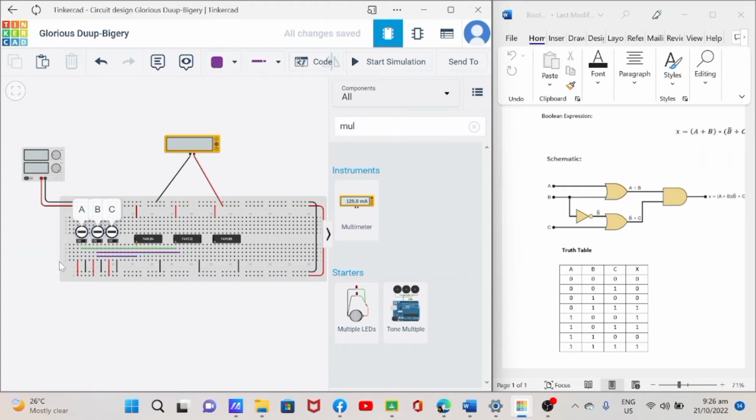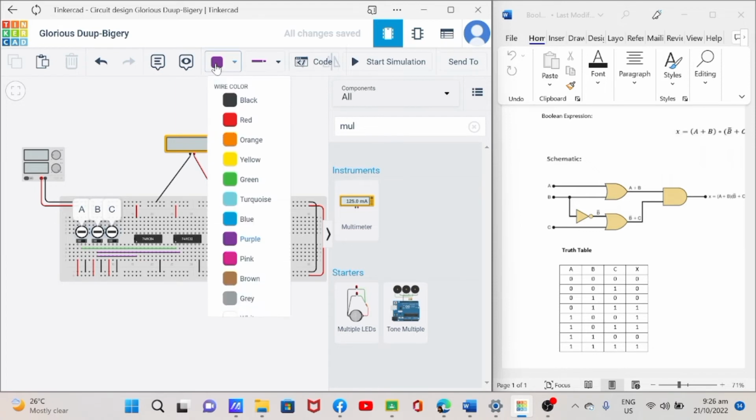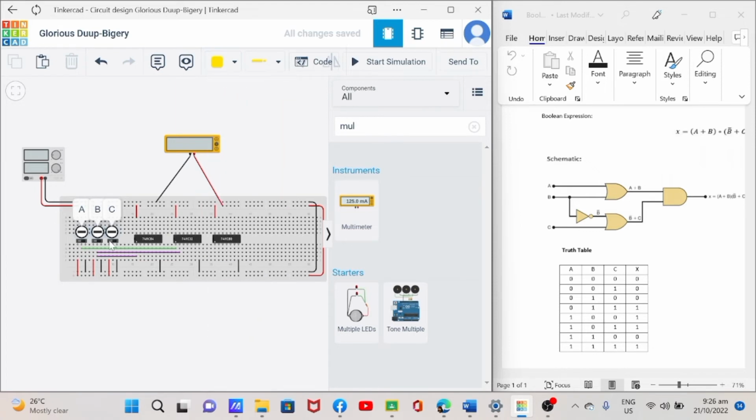And our input letter C is also need to be connected in our OR gate, since input 1A and input 1B of our OR gate is already filled with switch A and B. Then we are going to connect switch C in our second input or input 2A.